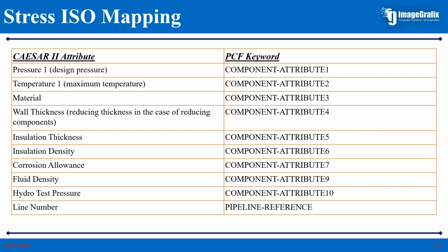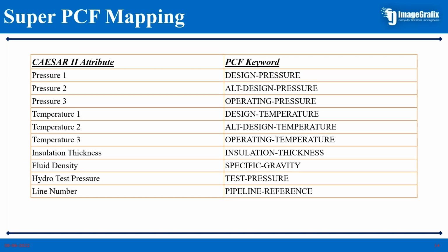And this is for your stress ISO mapping PCF, and this is for your super PCF mapping, which holds good for our CADWorx to CAESAR II integration. So this super PCF mapping is what we'll be seeing today, with pressure 1, pressure 2, pressure 3, everything we'll be seeing today.